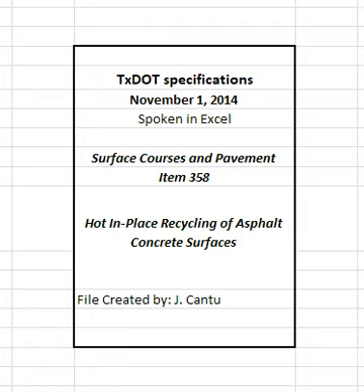6.3.2 New hot mix asphalt. If applicable, control the quantity of new HMA added to the recycled mix from haul tickets to within 5% of the target JMF. 6.3.3 Depth of recycled material. Maintain the required nominal depth on both outside vertical faces and in the center of the recycled area. Manually measure and report recorded depths each 1/4 mile, approximately each hour of production. Measure from the bottom of the mill pass to the top of the surface placed.